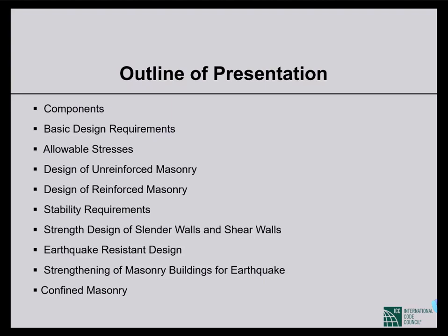We can estimate the effect of stiffness for lateral load using a strut model, but in general, we cannot use only a strut model for a load-bearing wall system, unreinforced masonry, because unreinforced masonry also takes gravity loads. So gravity loads and lateral loads, all those loads are considered to produce in-plane stresses. That's why plane strain elements are used in modeling.